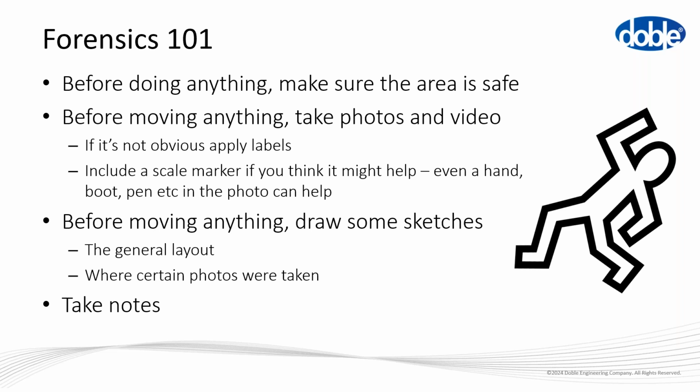And if it's something where, take a bushing failure, where things are going to be possibly exploded over a large area, draw sketches, map out where the pieces have ended up, and take copious notes, because once you've moved it, you won't remember. You'll think you'll remember, but by the following day, after you've had 10 other conversations about failure, you'll have forgotten certain details. So photos and notes, really, really important.